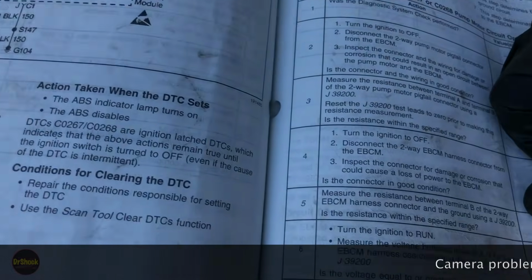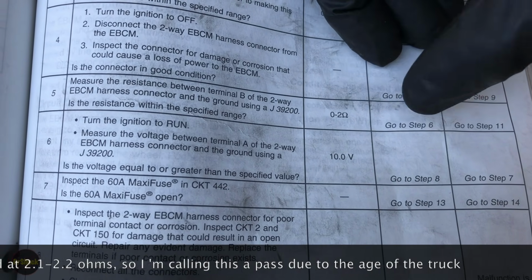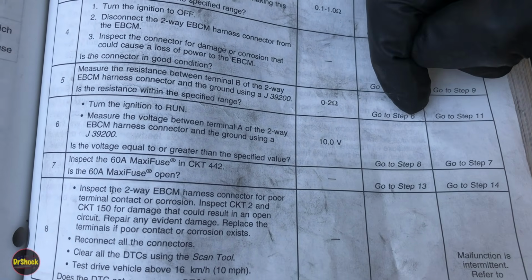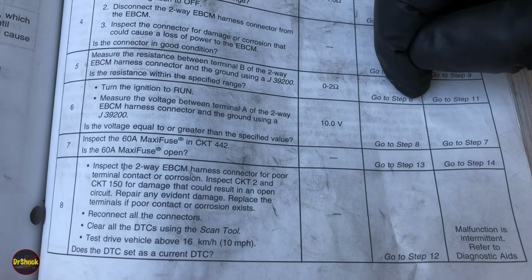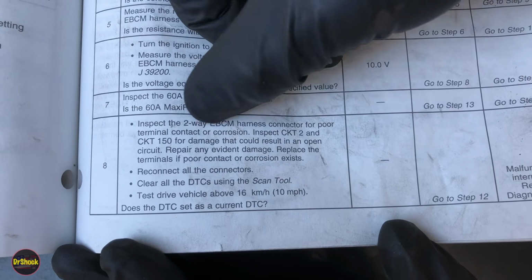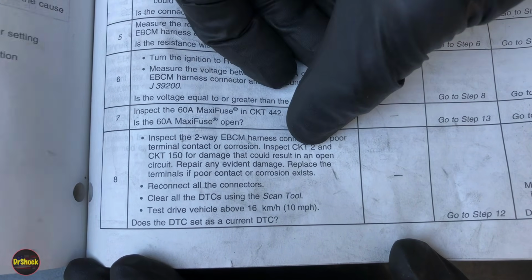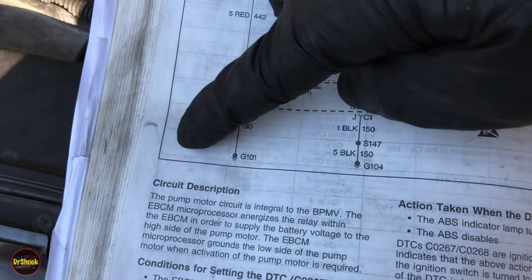And you see here with this spec here, if we got anywhere between 0 and 2 ohms, this test is good. If we get that, we would have gone and done this voltage test, right? Now, we could go ahead and do that voltage test. In fact, let's do it, right? We'll go ahead and put that test in, and where we're going to end up is, if that passes, it's going to take us right back to the same thing, where it's going to say, hey, you have some kind of a problem with ground, and you're going to need to chase an open or poor connection or corrosion on circuit 150. Now, they got circuit 2 on here as well, but circuit 150 from our schematic up here is what would have been concerning.